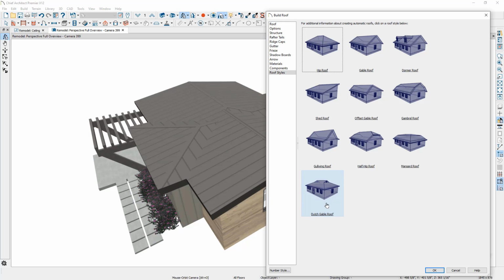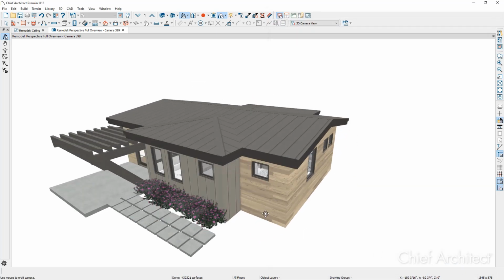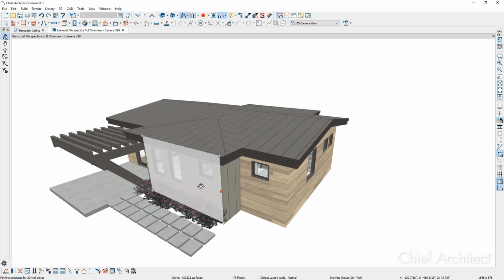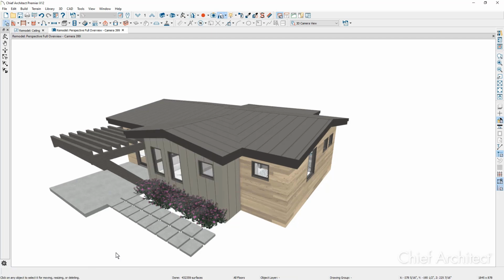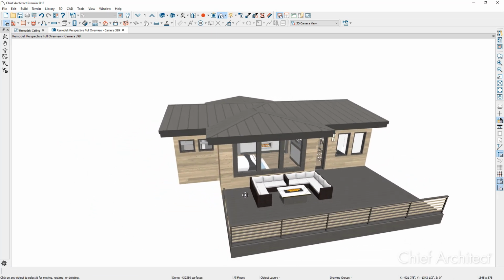And these are typically controlled through the wall settings. As I rotate around and look at the front of the new office, if I click on this wall, there's a tool to convert this wall to a full gable. And since the automatic roof is on, it will automatically update the roof when I make that change. Rotate around to the back side where the master bedroom is.